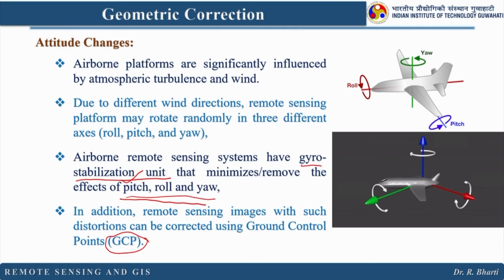In the image, if you know that this pixel is supposed to belong to a forest area, then you can match the ground control points and that pixel location, whether they are the same or different. If there is a change in the latitude, longitude value of the image and the ground, then you need to adjust the error of the image, right, because the measured values, the ground control points, are the true values.